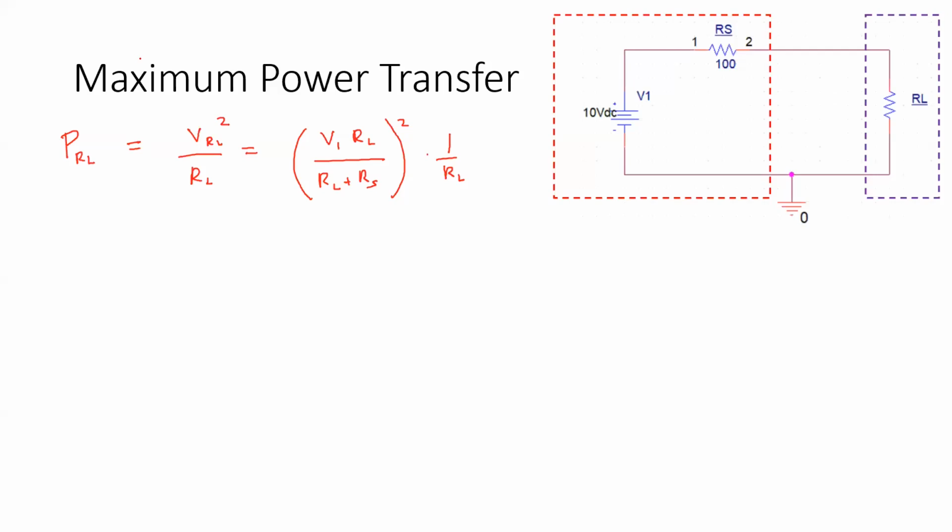Now, when it comes to achieving maximum power transmission, we can consider the same circuit. So here I have written PRL, that is the power dissipation from this load resistor. So if we have the maximum power transmission, we should have maximum power dissipation from RL, because it's a passive device. So if you write the equation for that, we can write V squared over RL. So RL we have already calculated in the previous section. So it's this one and this one.